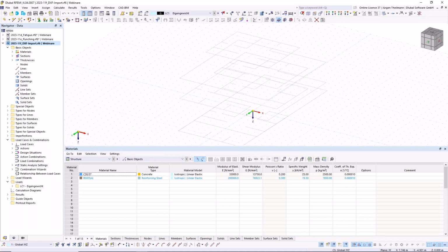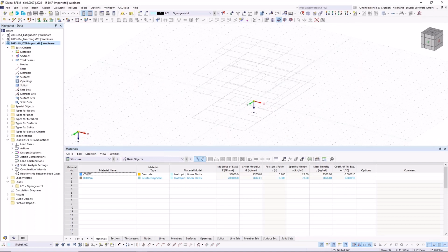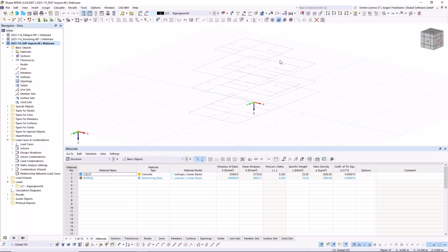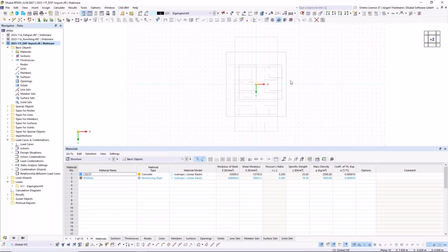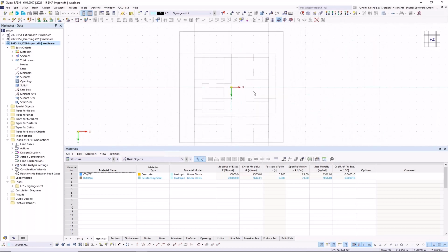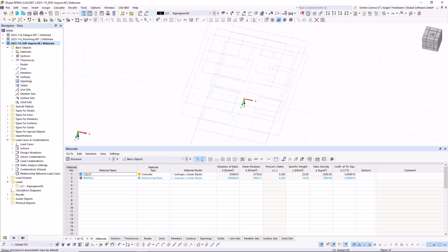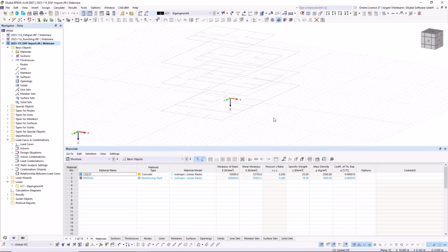And here I have a small multi-story building. So I have 4 background layers inserted here. And what I intended was to have this, when you follow my mouse pointer, to have this wall be on top of each other in all stories of my building. But when I look on it from the top, you can easily see, oh, I have got something wrong with implementing my background layers in the file. But that's not a problem. That is now easy to correct.